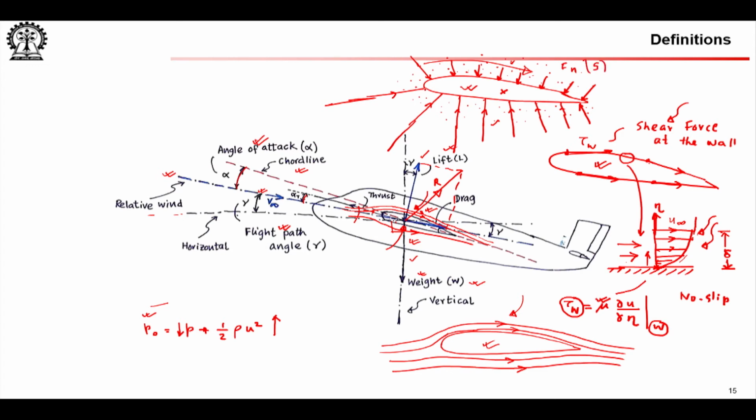So, S you can think of starting from the front stagnation point, you have a wall fitted coordinate system S, and normal force as a function of S. Similarly, if you start from here and you define a coordinate like that, you can also say wall shear force as a function of S. Using these two distributions, you find the resultant force acting on the airfoil cross section, and that is R. Then what you do is you resolve R into a force perpendicular to V infinity.